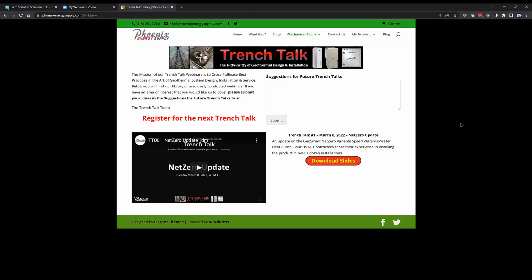And certainly many years ago, we used variable frequency drives on end suction pumps, and that's still a common practice. But when you look at the turn down capability, it's just not there. In these systems, we want to see turn down to about 10% from peak load, and typically we don't see that with VFDs. But if you're just going to throw a fixed speed pump in and let it run and ride the pump curve, yeah, you're looking at 85 to 90% energy savings.